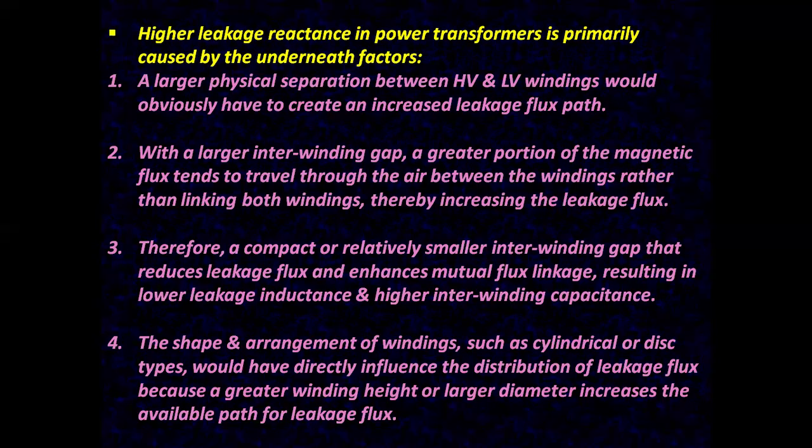Number 3, therefore, a compact or relatively smaller interwinding gap reduces leakage flux and enhances mutual flux linkages, resulting in lower leakage inductance and higher interwinding capacitance.